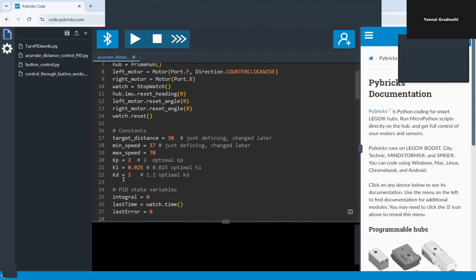But if it jumps from 16 millimeters error to 40, that's a very fast jump. And basically, it tells it whether it should slow down to make it jump less. Like how quickly is the error changing, and should it slow down to avoid overshooting. Basically, it predicts where the error is heading, damps the oscillations, and helps smooth the response.